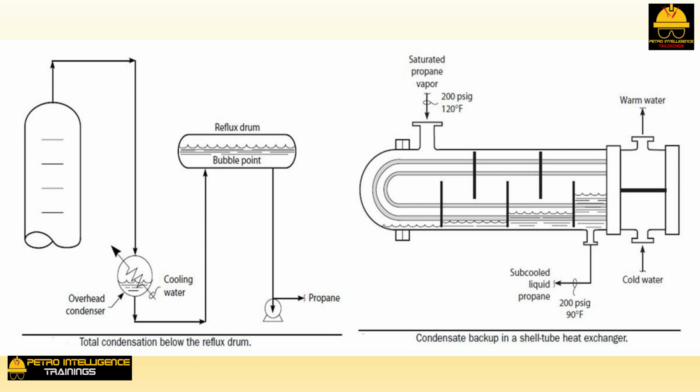1. If the supply pressure of the condensing vapor is fixed, the rate of condensation of the vapor will fall. In an apartment house in Brooklyn, this means that your bedroom will get cold. 2. If the condensing vapor flow rate is fixed, the condensation pressure will increase. If you are operating a debutanizer in Texas City, this means that the tower's safety release valve will pop open and release a cloud of butane over Lamar University.